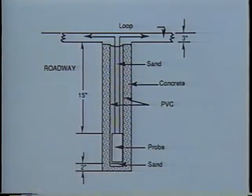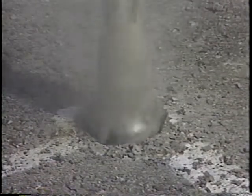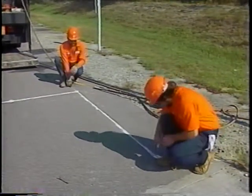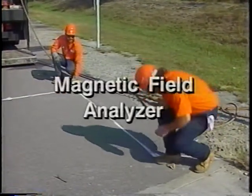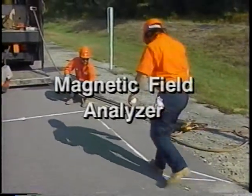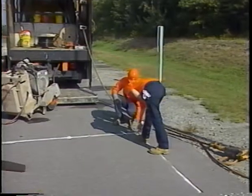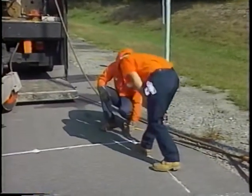Typically, the installation of a microloop and a magnetometer involves the placing of probes in cored holes in the roadway. The best depth and layout of these probes depend on the type of detection required by the site. After securing the work zone and marking the detection area, use a magnetic field analyzer at each marked probe location. This verifies that the area is free of any elements that would degrade the detector's performance.